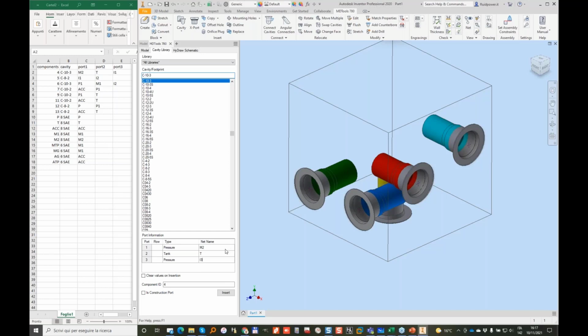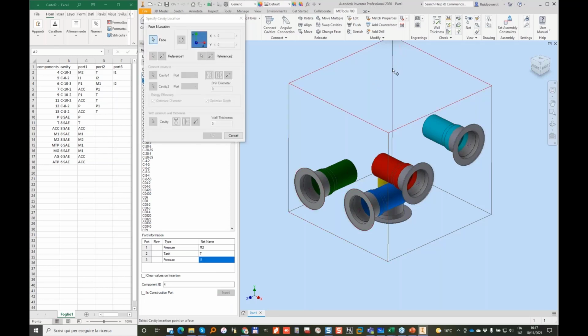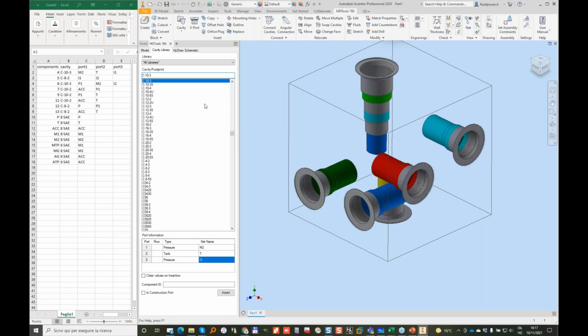So it was not made on purpose, but as you understand, when you try to fill in this data manually, you need to pay attention. When you design starting from a HydroCAD diagram, you import directly an XML file. So all this operation, which I'm trying to do as quickly as possible, which is taking time during this presentation, really it's reduced. That operation is error-free if you have made properly all the connections in the diagram. I place randomly, no problem.